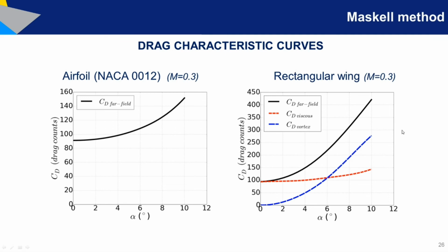And as you can realize, this overcomes the problem that we had before with the near field method. With the near field method, we were able to decompose drag, but the decomposition was identical for 2D cases and 3D cases, which was not so physical. In this case, we have something that really changes from 2D to 3D. It's crystal clear what's new in 3D phenomena.